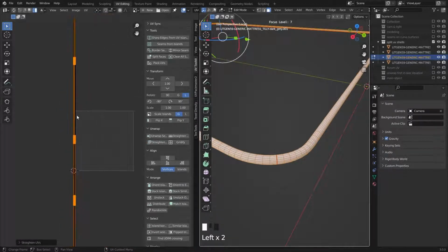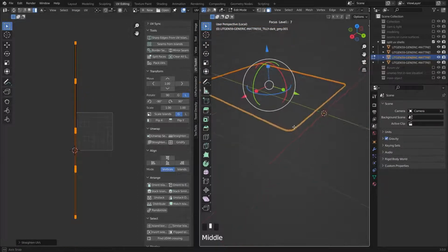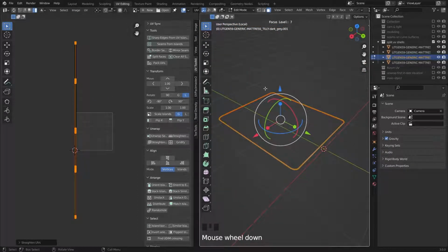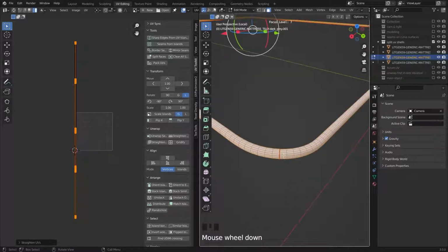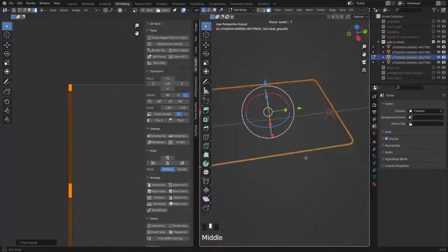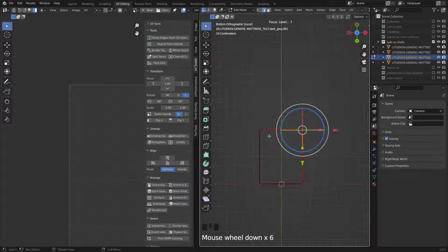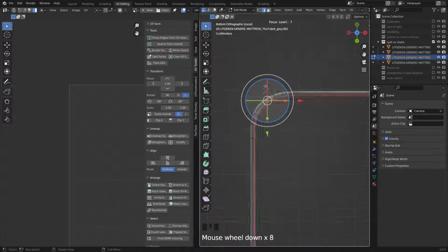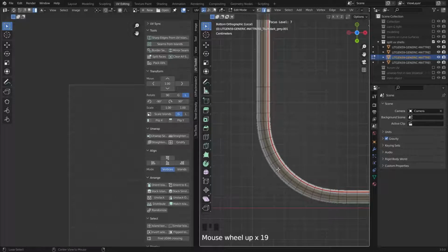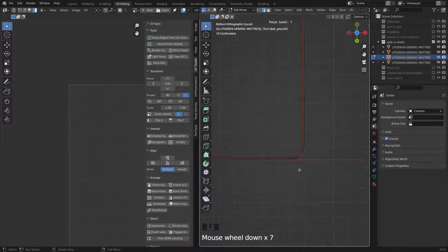So the important thing is, it's a really long pipe, and if I just put one edge seam, you can see I cannot use most of my texture space even if I pack it inside. So in this situation I prefer to split my object into 3 or 4 parts.